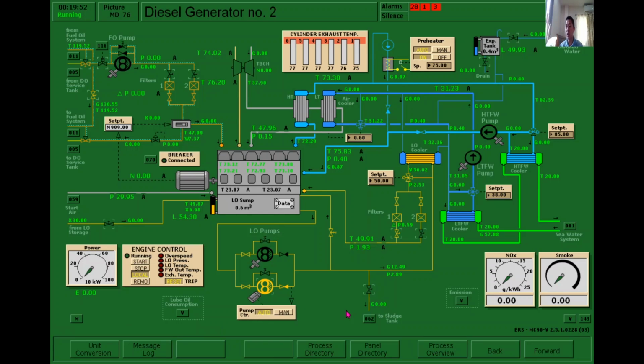Secure start air system, number 7 requirement. The student must be able to secure the starting air from the compressed air system to prevent accidental starting.